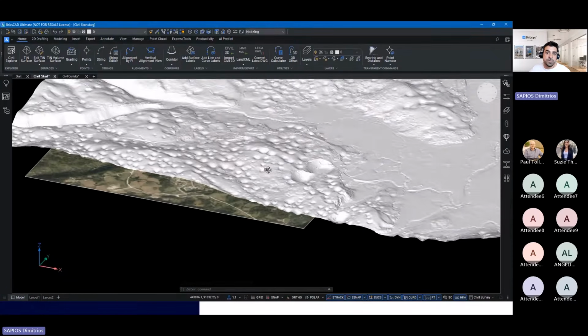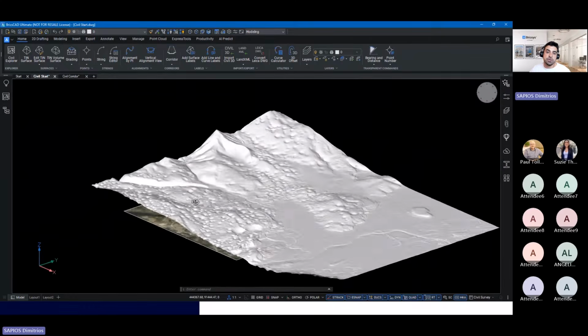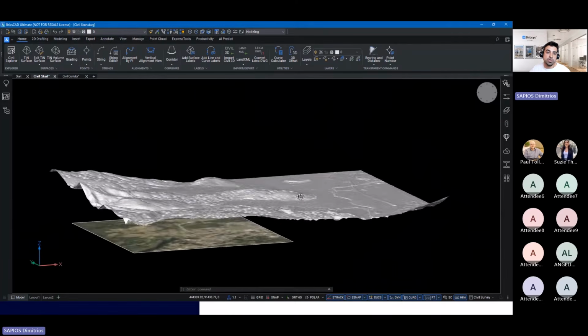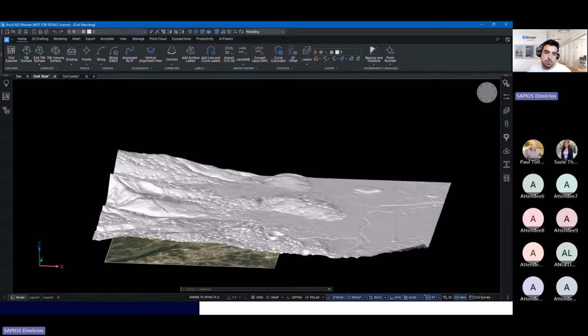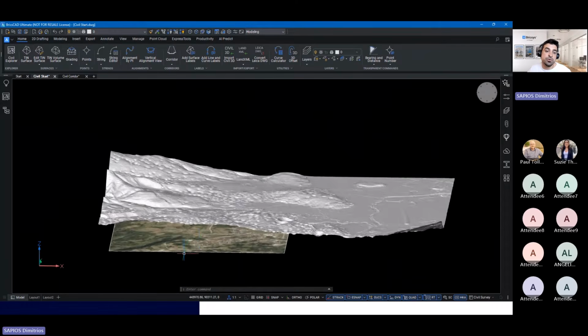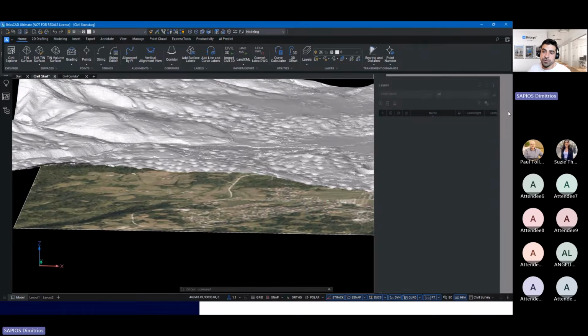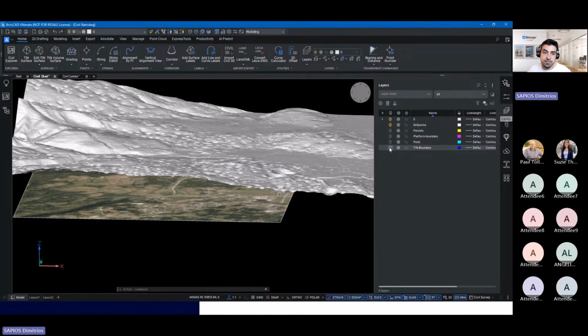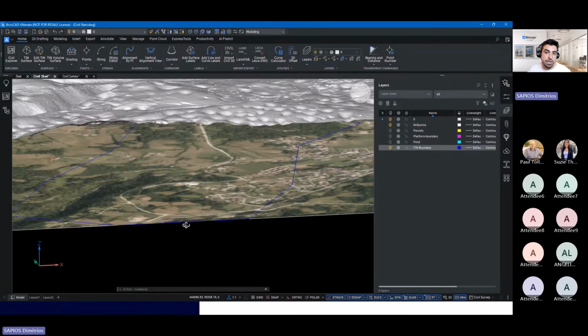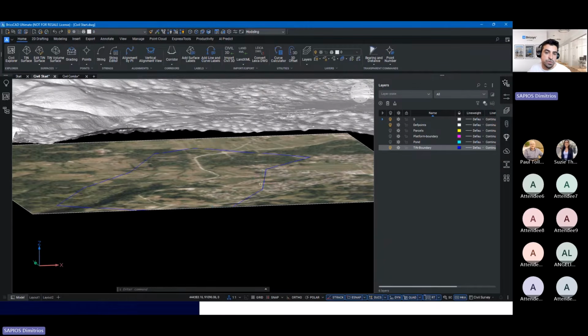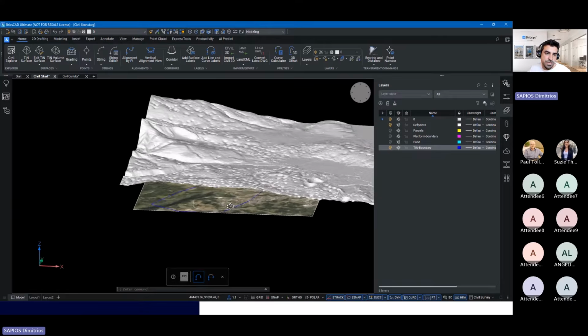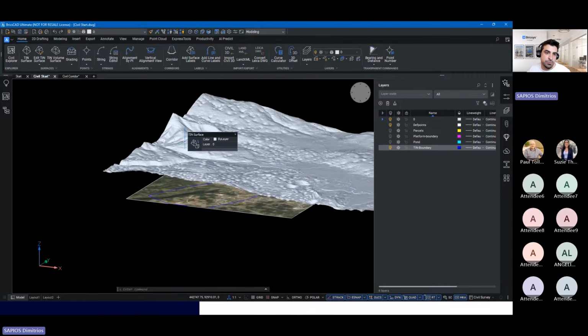And in order to make the drawing a bit lighter, I want to isolate and focus on a more specific region of the map. For this example, I've already created a blue polyline that represents the boundary I want to use. This is a 2D polyline. So in this case, I want to add the boundary, but I'm not entirely sure what the command is.